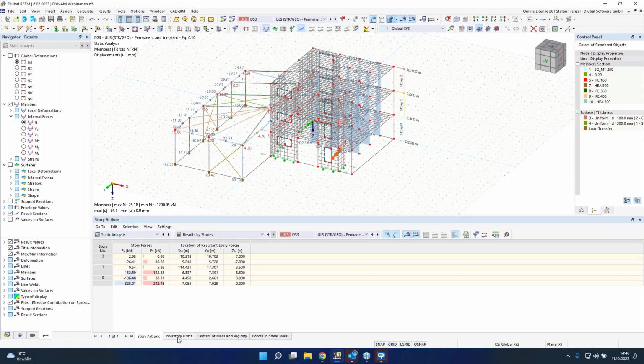So I can use my normal loads and don't have to consider the earthquake calculation in it. What's also important here is that you have for this building model also the option to have a look at the displacement for the interstory drift. That is also important because we want to bring in the future an add-on module which is called pushover analysis, and therefore you need, of course, the interstory drift. Here it is also important to know what to do by hand calculation now, but maybe in future we can do it automatically, to calculate if you have to consider the second order in earthquake analysis or not. That is also a point for that.